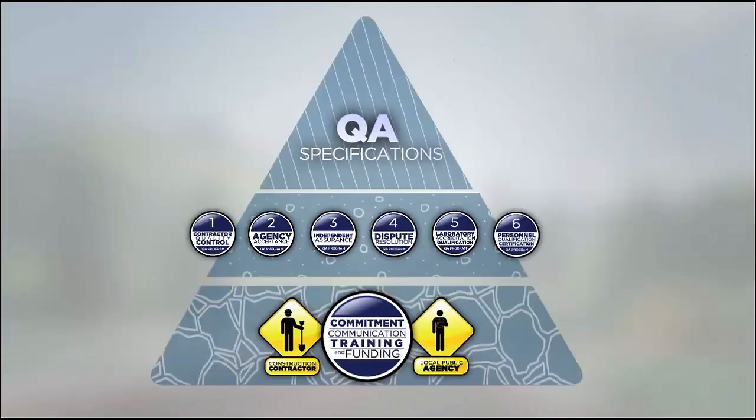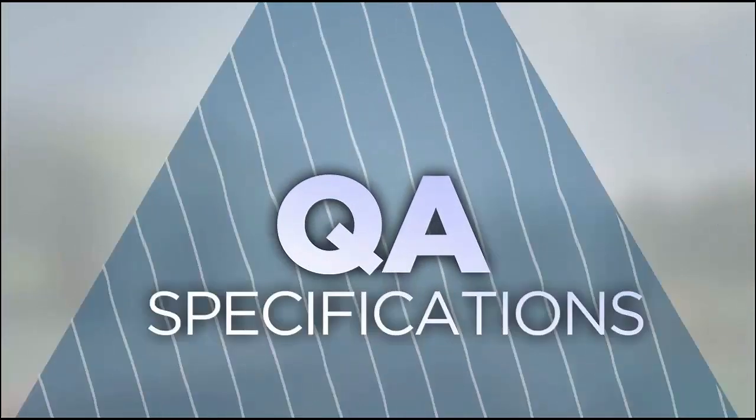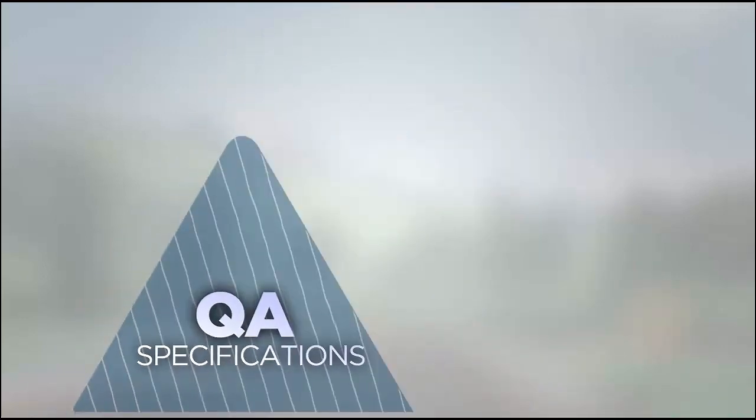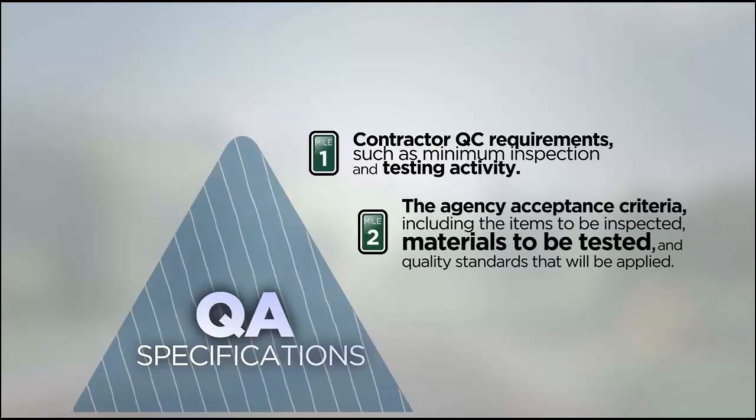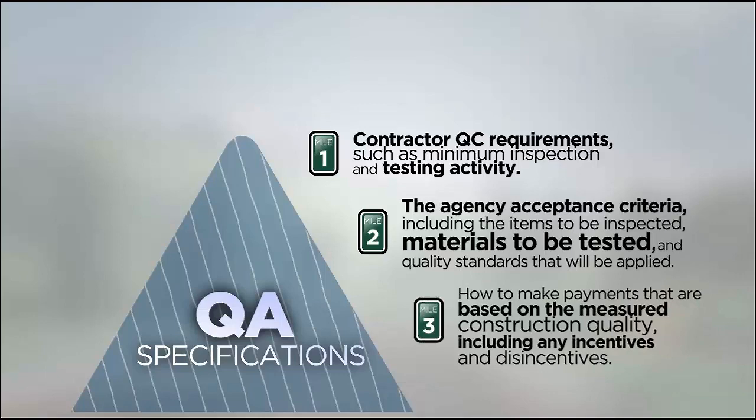The third tier of the pyramid is quality assurance specifications. These provide project-specific instructions for implementing the QA program which will be included in the contract. These specifications include contractor QC requirements, such as minimum inspection and testing activity, the agency acceptance criteria, including the items to be inspected, materials to be tested, and quality standards that will be applied, and how to make payments that are based on the measured construction quality, including any incentives and disincentives.